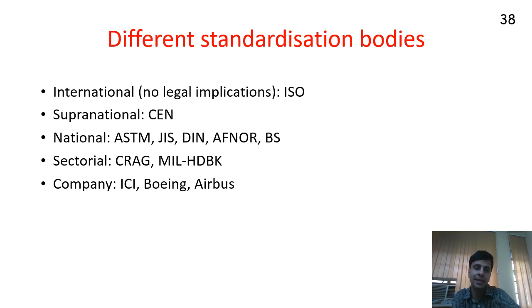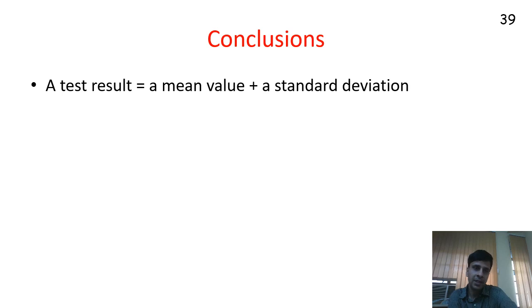No, scatter is too high, let's do 1 inch, calculate the scatter, etc. I don't have to go through the iterative process that you went through in your simulation. There are standards. I can just open up the standard and say that I am doing the test according to, let us say, the ASTM standard. There, clear definitions about the length, width, thickness, etc. will be provided.